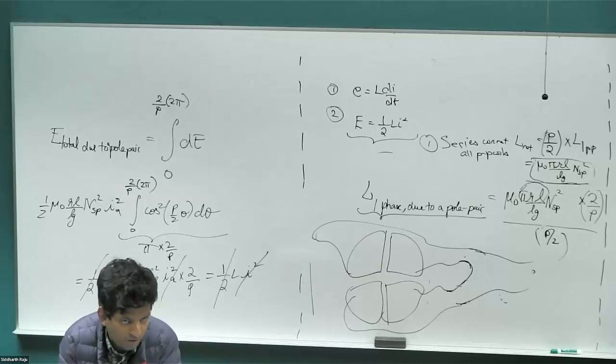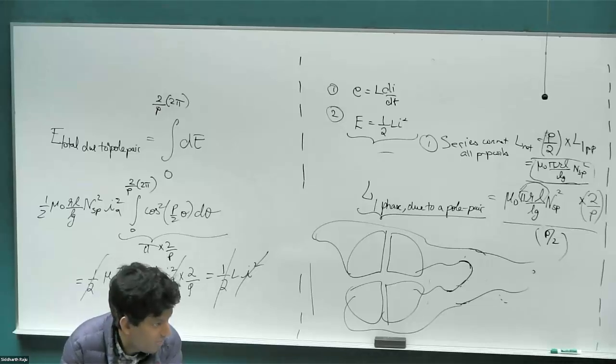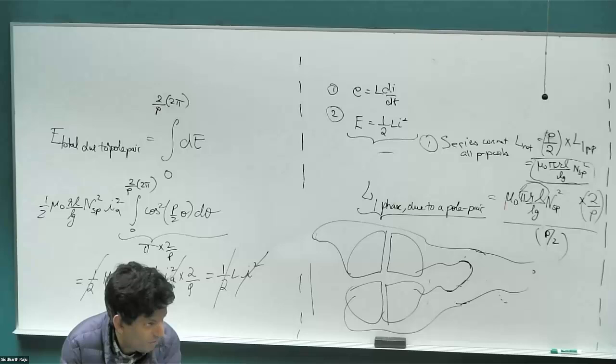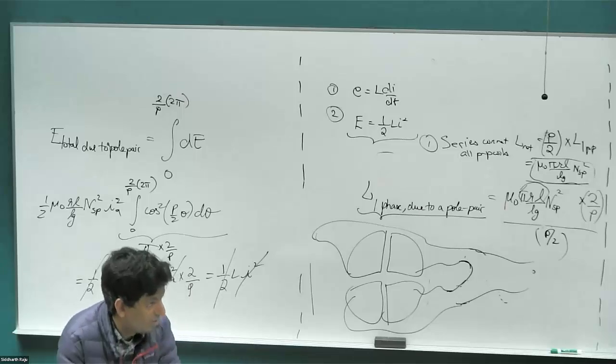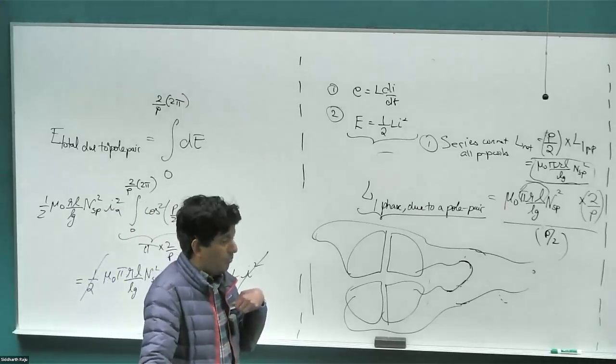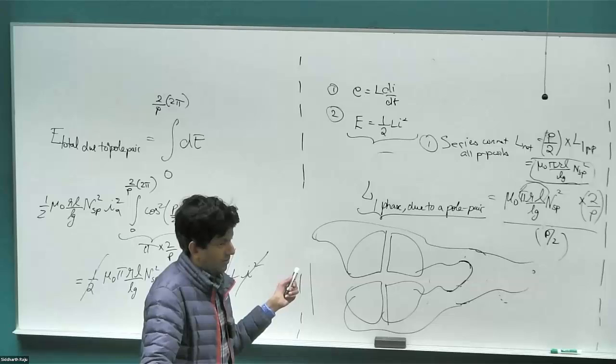So if you want to split the current up because the current is too large to handle, you would wind them in parallel. When would you connect them up in series? Yeah, Chris. Is that if you wanted more torque? You can create more torque in either of those arrangements. Well, I guess it would just be more current. Would you repeat it? Wanted more current through. If you wanted to put more current, you would have to split them in parallel.